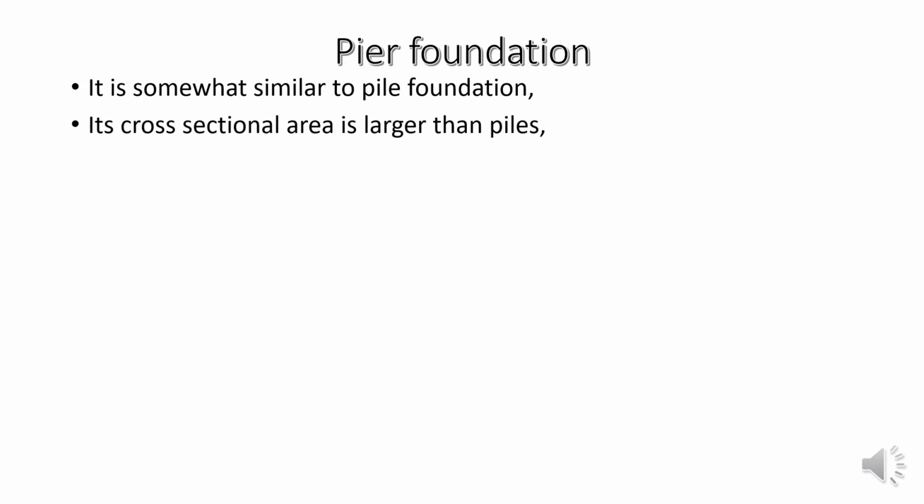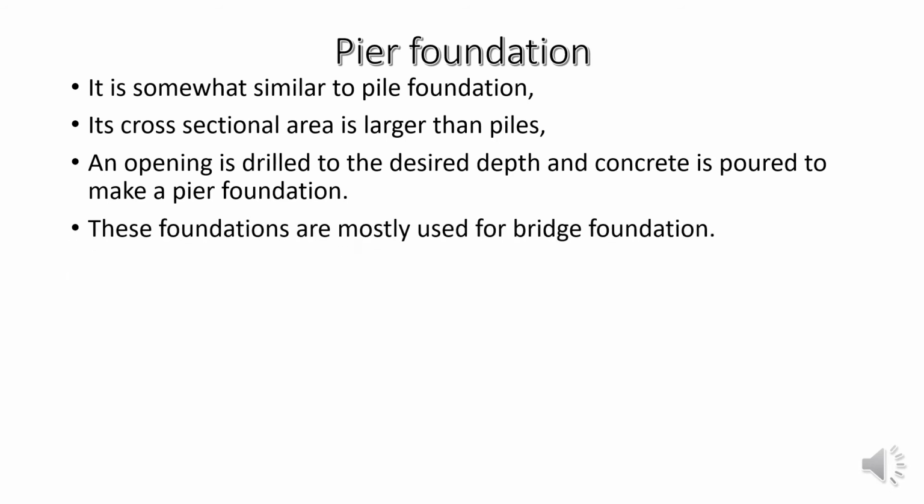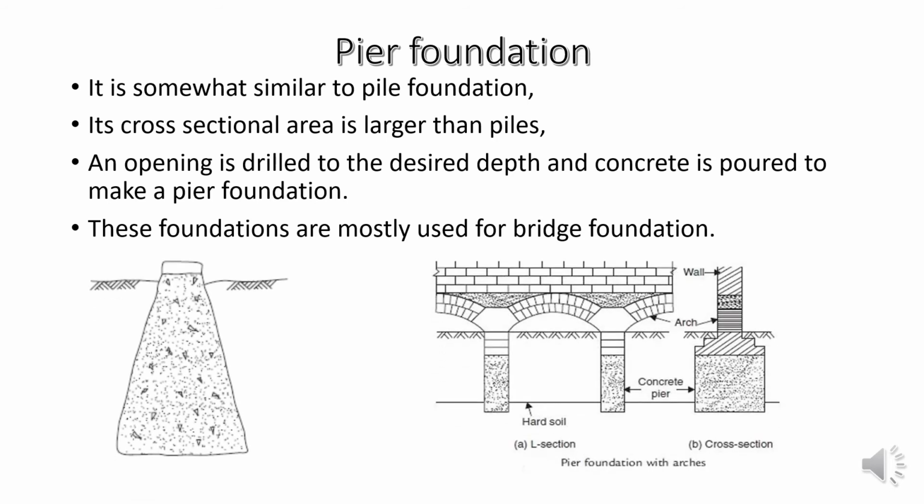Pier foundation. It is somewhat similar to pile foundations. Its cross-sectional area is larger than piles. An opening is drilled to the desired depth and concrete is poured to make a pier foundation. These foundations are mostly used for bridge foundations. The figure given below shows the pier foundation.